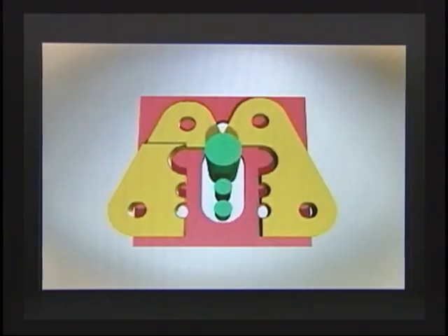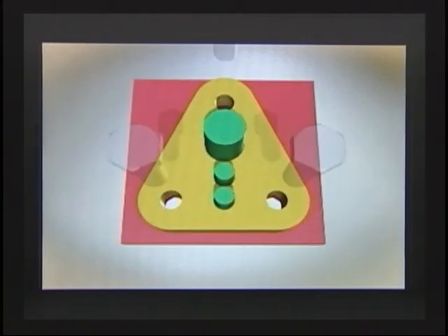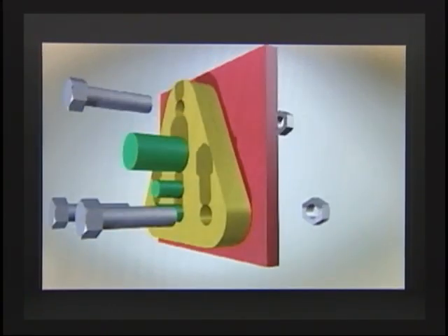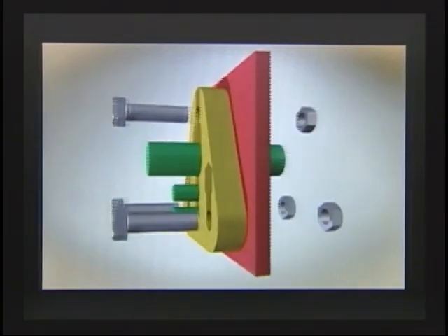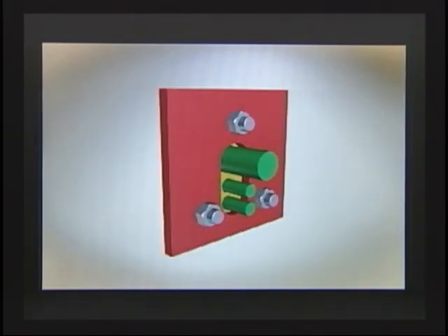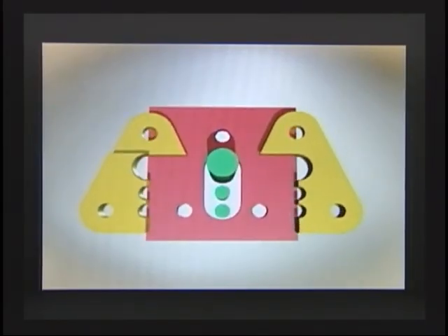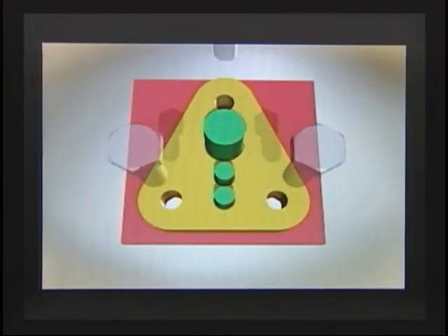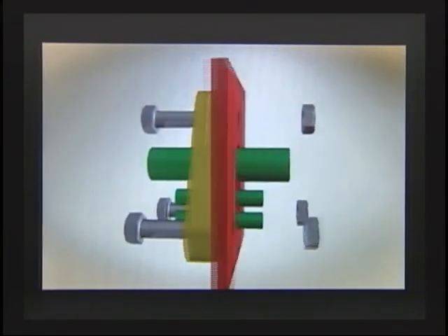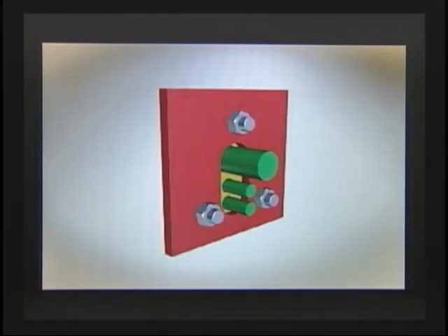And once they seal over the cables, you notice up on top we have to have our gaps controlled all the way around to make sure our gaps are according to the drawing that we saw earlier. And here the parts are going to come together. You see I'm going to put the bolts in on the back side, put the bolts through, and we tighten up the nuts. Let me just show you that one more time so you can see it. There's the two pieces coming together. They seal around the cables. We're going to put the 3/8 bolts through, put the nut on, and that's our assembly.